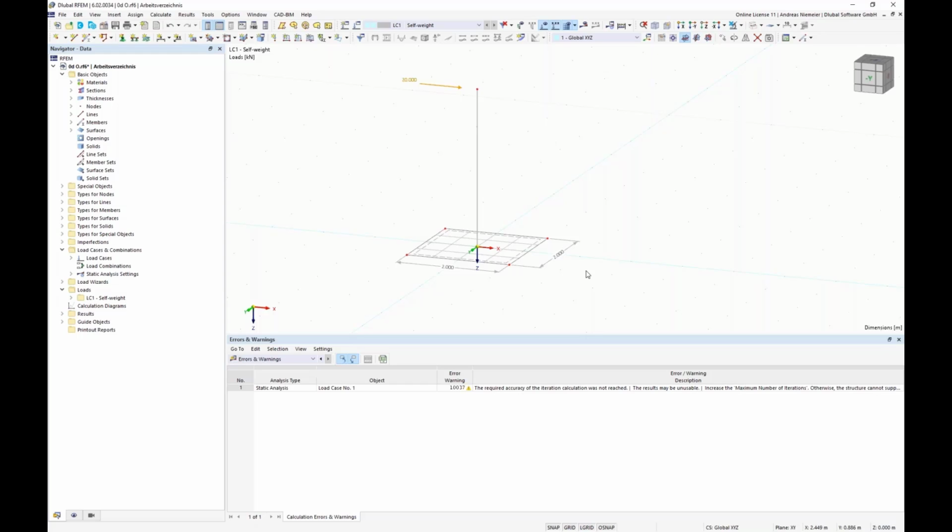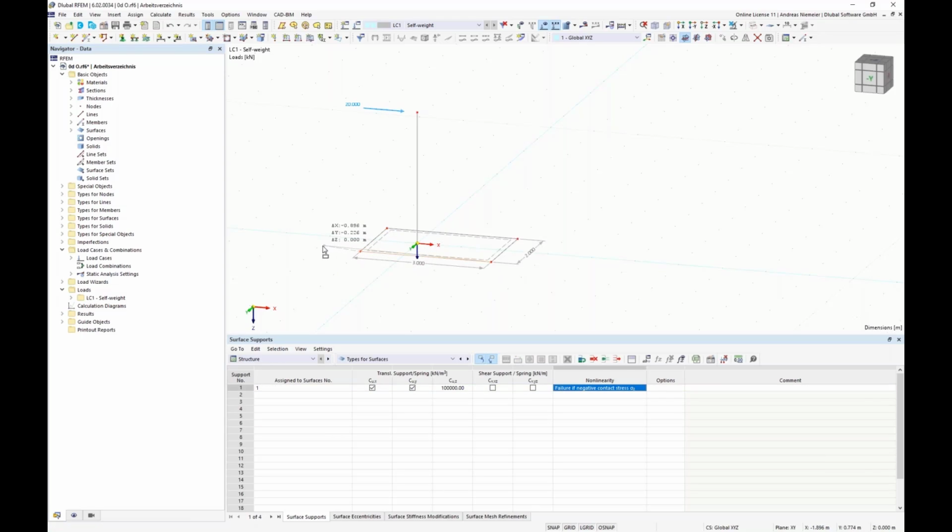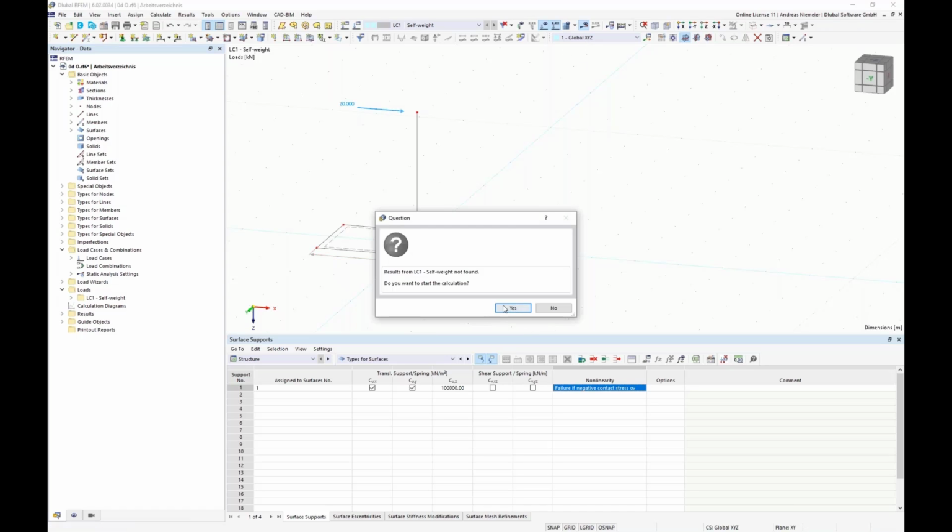Now, what we can do if we should take over this horizontal force with this structure, we can only modify the size of the foundation plate. And because we don't know which size is good, we try to optimize the structure at first manually. For me, I select these nodes. I do these changes always symmetrically because I assume the force can appear in both directions. So I increase it by double, from 4 to 2 meters, and start a calculation.